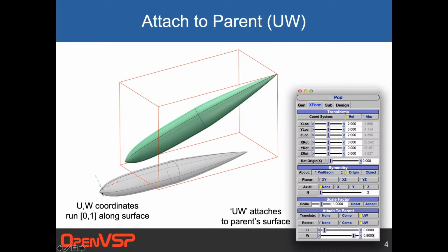So what we have is we're slightly offset from the nose in this coordinate system, and then the green is 2, 2 in XZ off of that. And that's why you notice that the absolute coordinate ends up with these odd values, and it's because of this rotation from this point. But you can use attachment to attach to the surface or just the origin of a parent component.